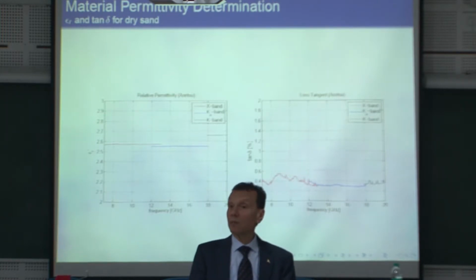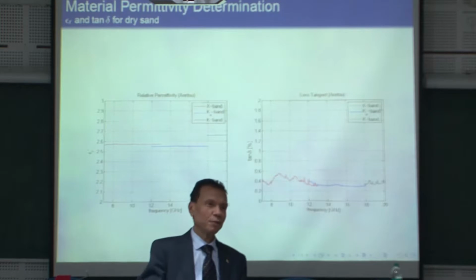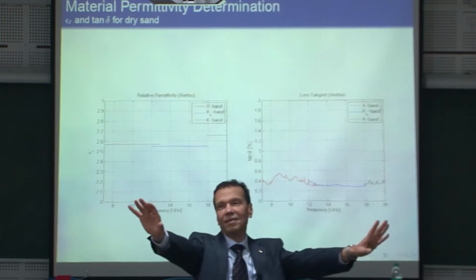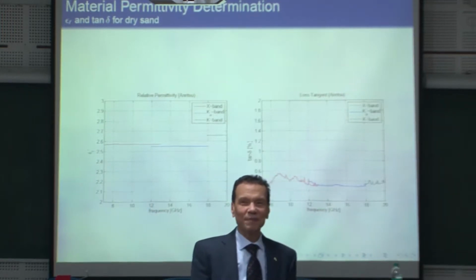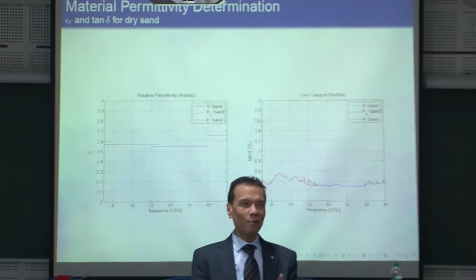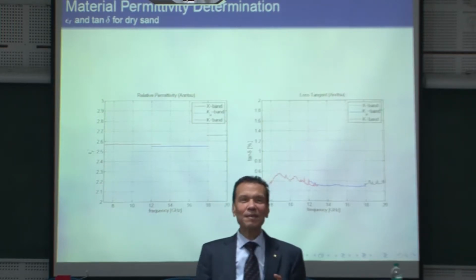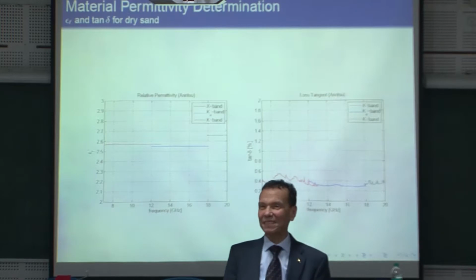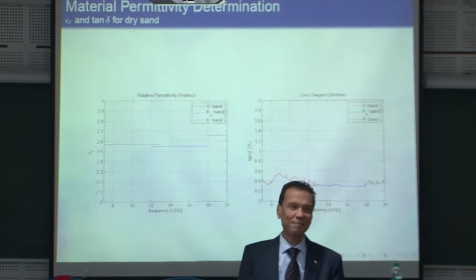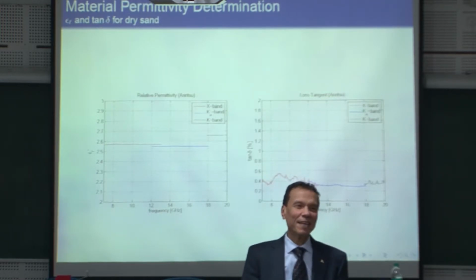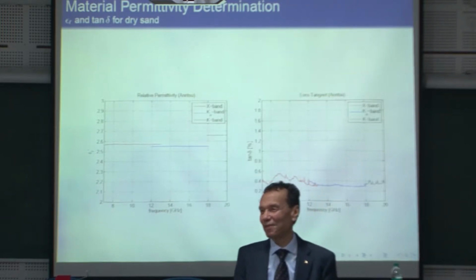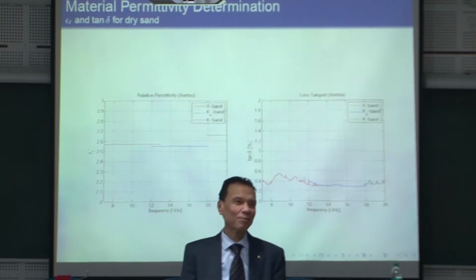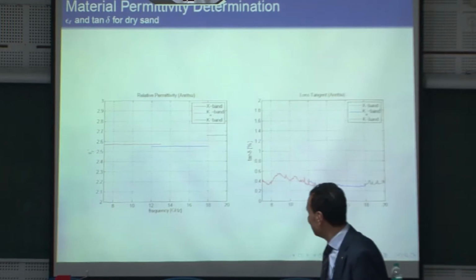And we filled it with sand. It became 1 ton. We had problems as we moved, when engineers of the university came and said, stop. We have a maximum load of only 600 kilograms per square meter, and you cannot put this box. We had to remove half of the sand from the box in order to cope with the regulations.